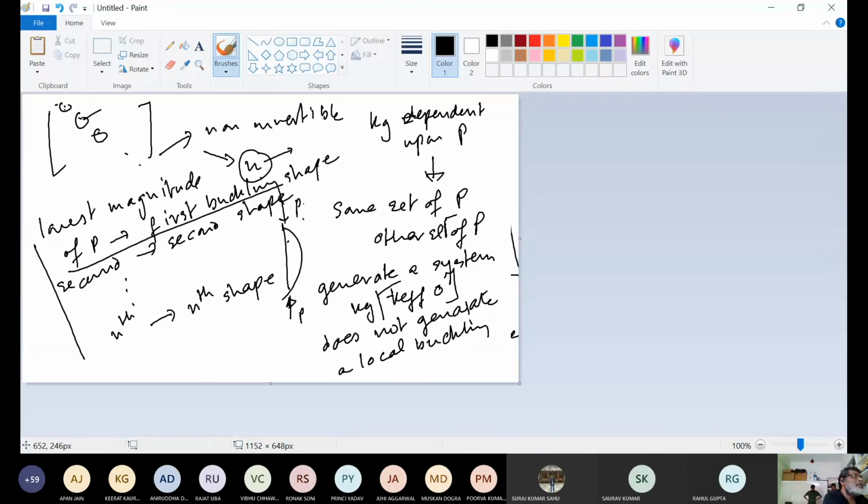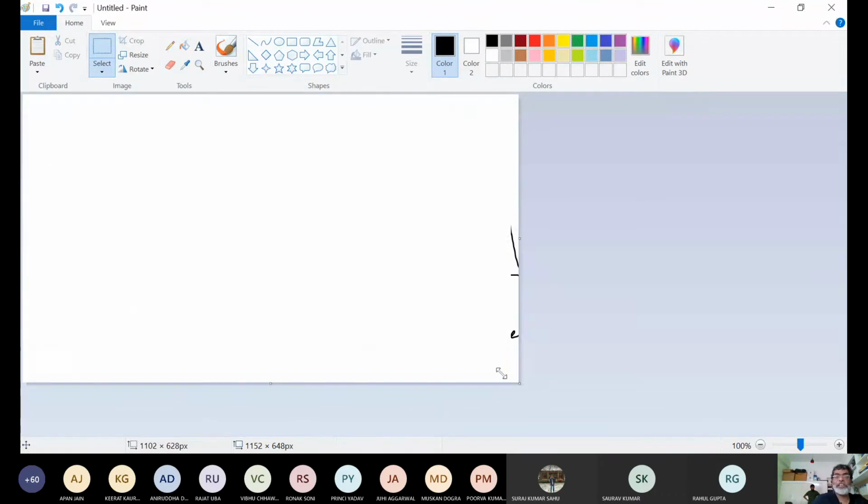And why is that the only thing that you worry about? Because if the global buckling happens after the member buckling, your member has already failed. You get my point. Now, the point here is that there are two things that we can take a look at. Let me just clear this and go back to my brush.